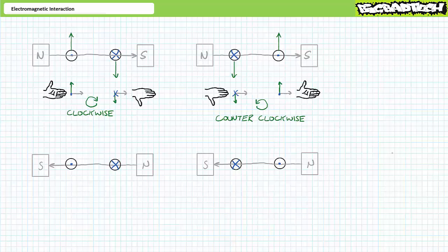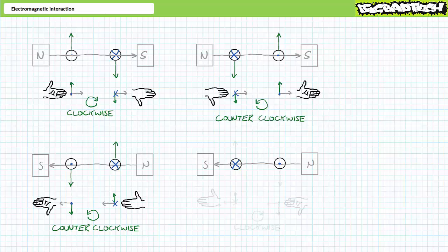This current-carrying loop would therefore be torqued counterclockwise as the electromagnet seeks alignment with the external magnetic field. For the third scenario, an application of the left-hand motor rule demonstrates the left conductor will be forced downward and the right one will be forced upward, such that the loop will be torqued counterclockwise as the magnetic field seeks alignment with the external magnetic field.